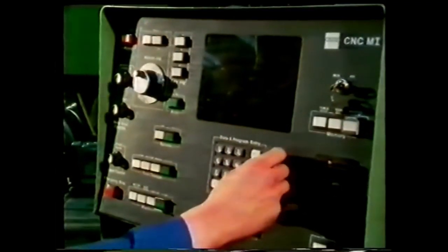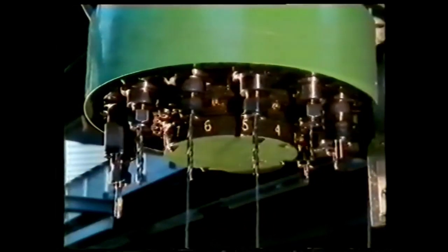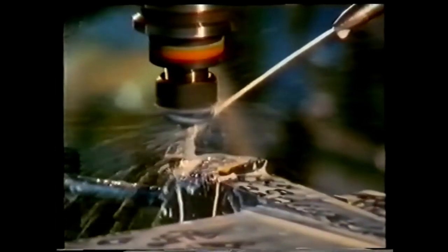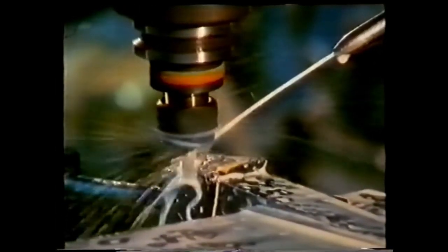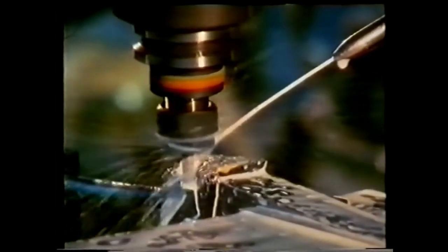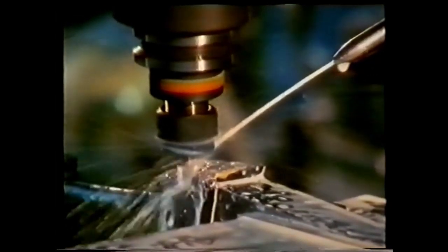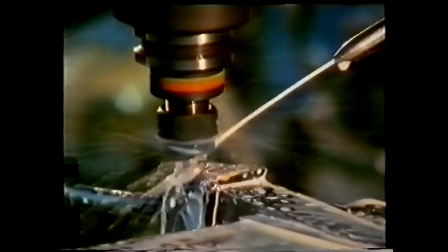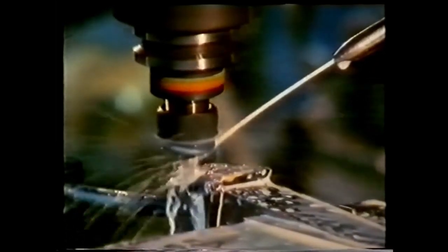To ensure a high rate of production and accuracy, CNC drilling equipment is used to form the clamping section into which the insert will be placed. Accuracy is essential. When the insert is changed, the positioning of the replacement must be identical so that cutting can continue without any need to reset the tool.